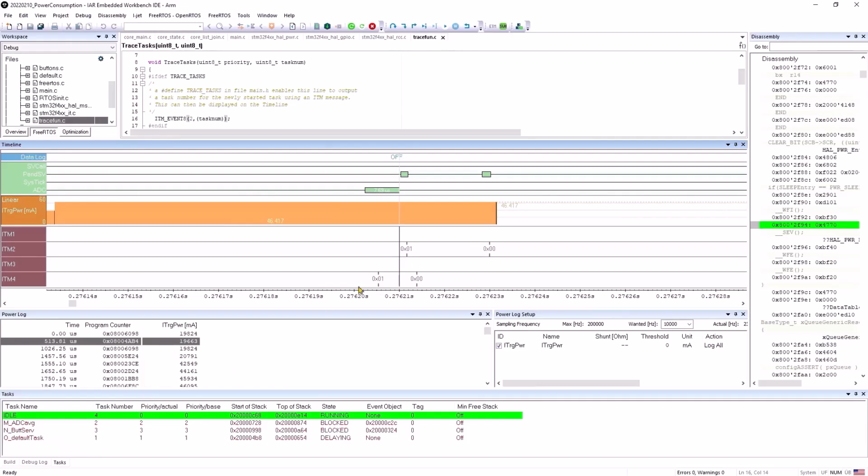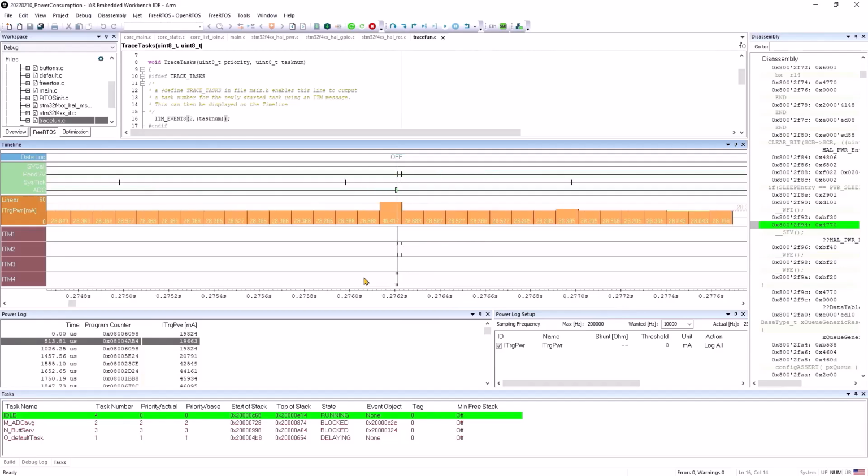So you can use this available information to get a detailed inside overview what happens inside your RTOS, and you can also see the relation between the interrupts that are happening and, for example, some peaks in the power consumption that might be triggered by some functionality that got triggered inside the interrupt service routine.